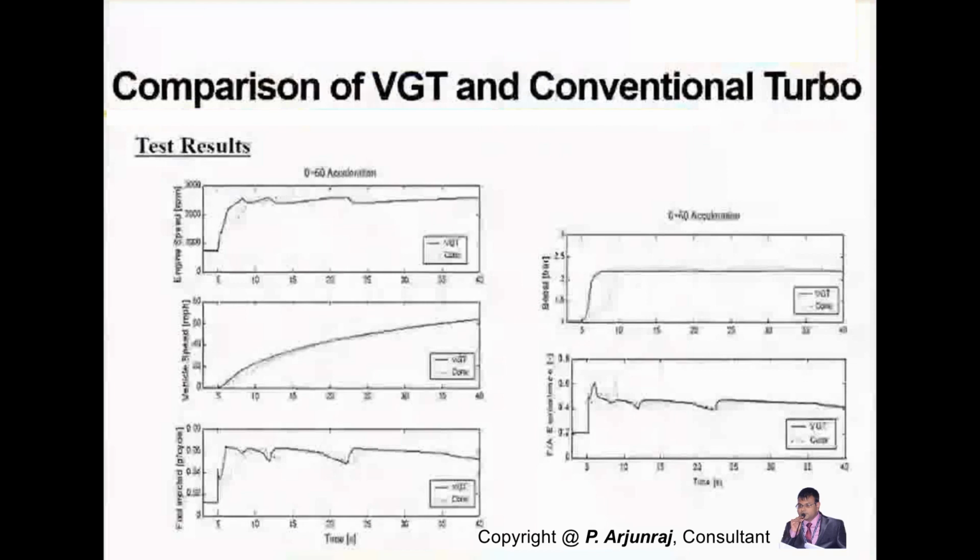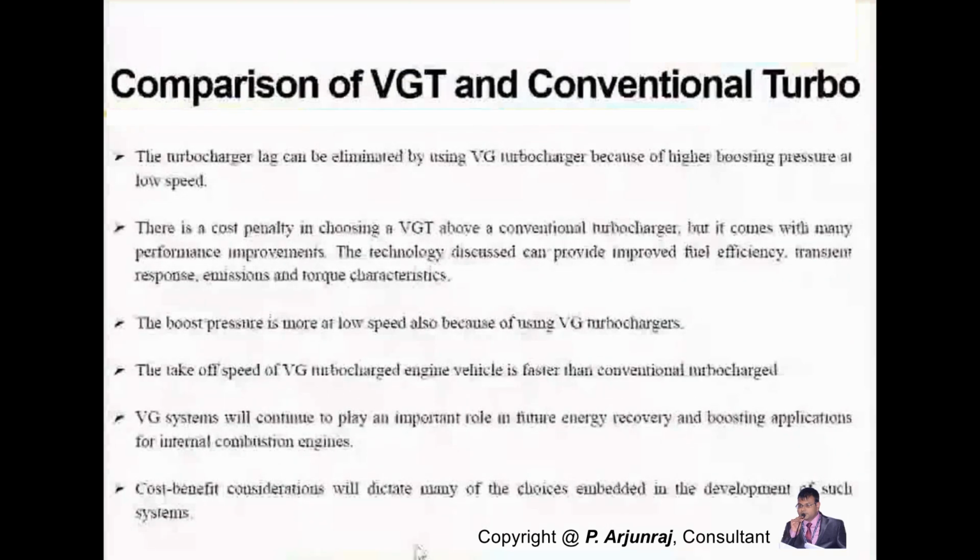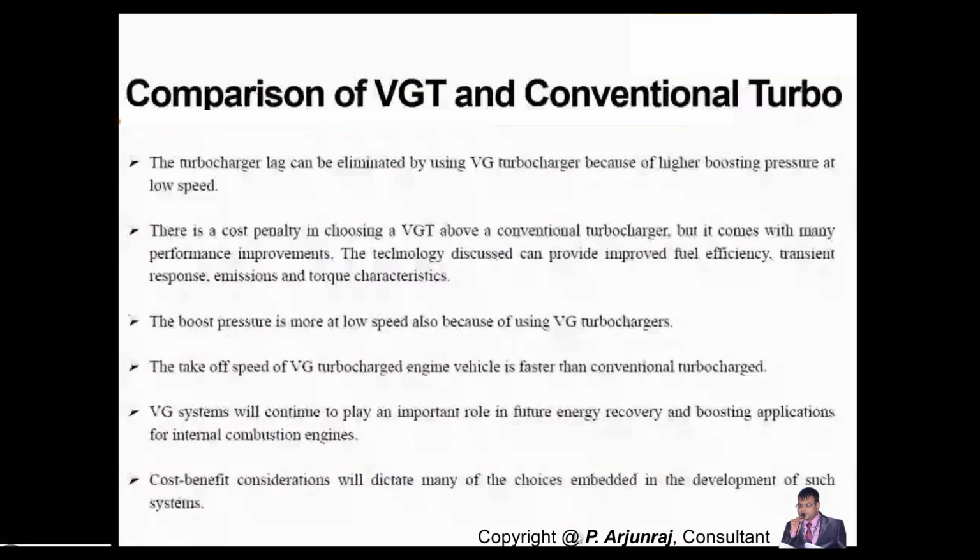So when I compare the variable geometry turbocharger and the conventional turbo back to back, the turbocharger lag can be eliminated by using the variable geometry turbocharger because of higher boost pressure at low speed. That will also help you to maintain the aspect ratio of your engine.